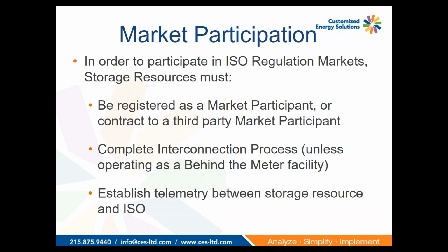The exception to that can be if a resource is operating behind the meter, meaning it's finding a consumer or a load and it's basically serving that load first. The restriction there, though, is it may limit the amount of storage you're able to provide because you can't export out to the grid.